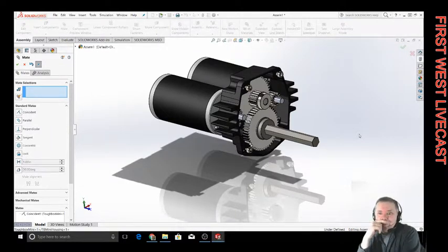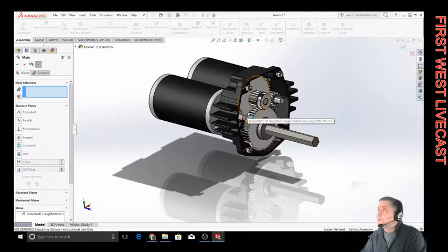As I say, the most difficult thing in SolidWorks to get a properly built model is you've got to make sure that it's properly defined. And you can see right here where it says underdefined. This indicates that this thing has some ambiguous dimension somewhere. It doesn't know exactly where it fits in space, either X, Y, or Z. There's some dimension in there that's undocumented. So a professional or a good SolidWorks modeler will make sure that this little text right here says fully defined. That's the cat's meow.